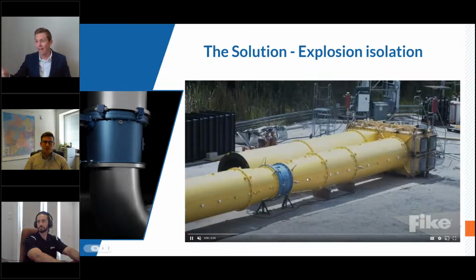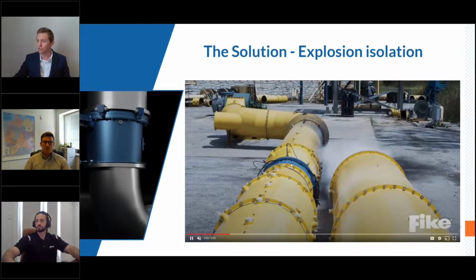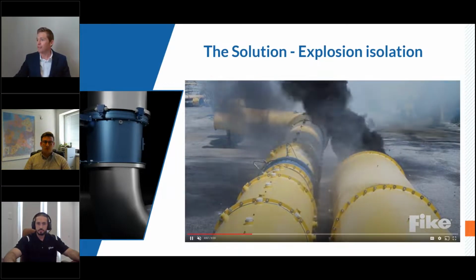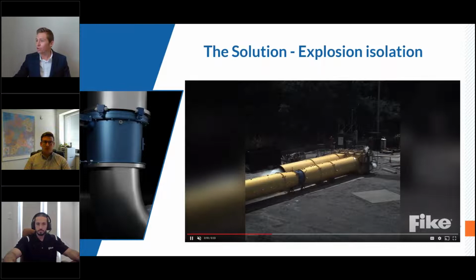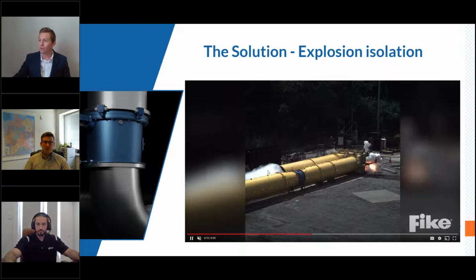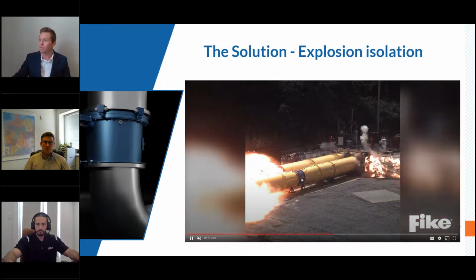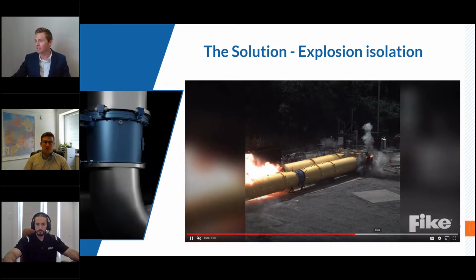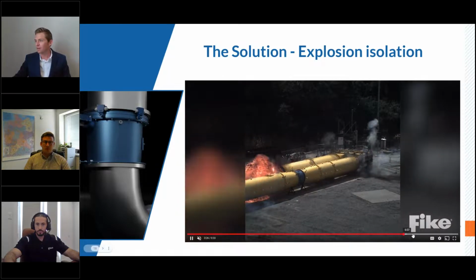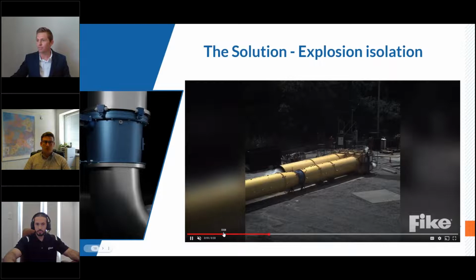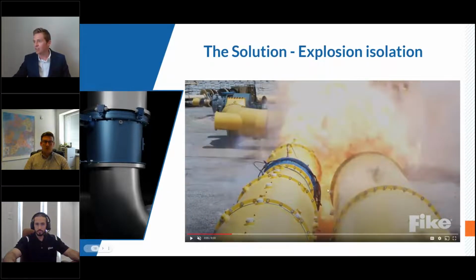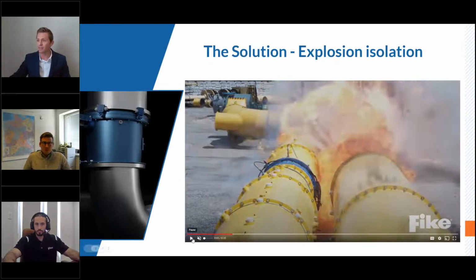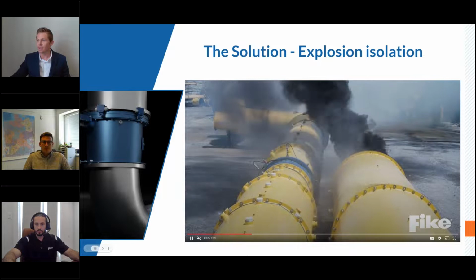Here's a real-time video. This is a loud video. You're not going to hear any of the audio though, but here it is. So this is a 32-inch diameter DFI, and here's the enclosure where the deflagration occurs. It travels back upstream. This is all unburnt fuel. Here comes the fireball. It goes back up the stream. It isolates it. Here's how you know it isolates it. Right here, you can see here's the explosion, here's the isolation valve, here's an open pipe and a fan pushing against it. Nothing. It's isolated.